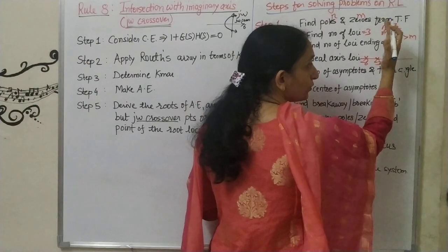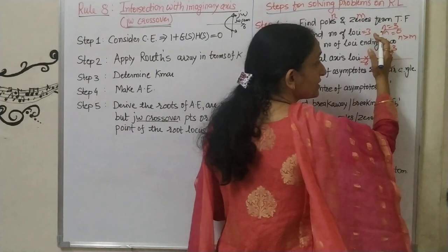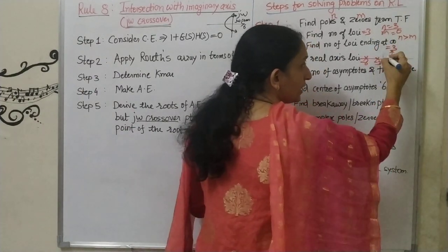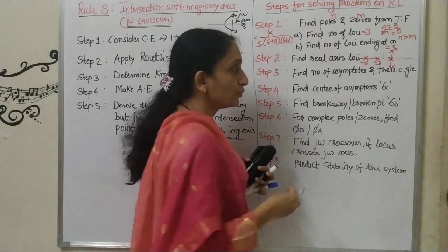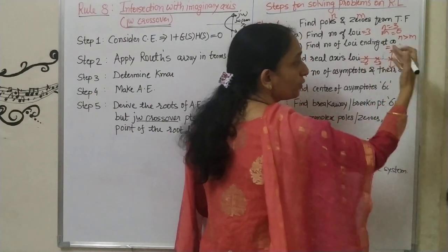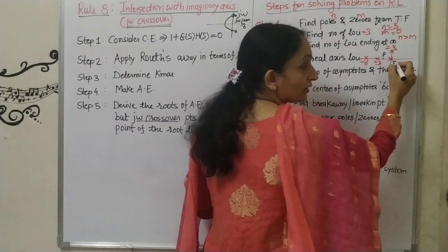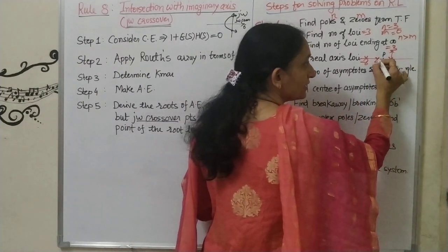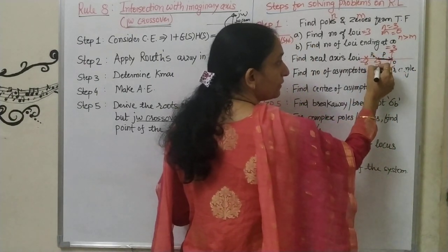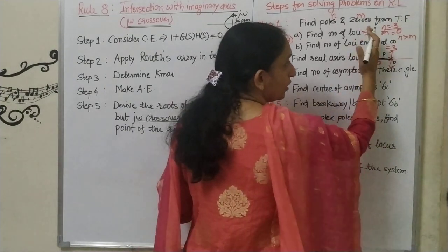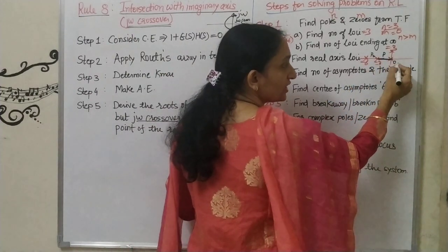Okay, so we know that what we are doing is calculating the addition of the number of poles and zeros on the right hand side of this point P1. If that addition is odd, then that will be the region on root locus. So we can check that here only one pole is there on the right hand side of this point P. So from this pole to this pole, 0 to minus 3, this will be part of the region on root locus. Then here I am considering point P2 in between minus 3 and minus 6. See here, on the right hand side of P2 2 poles are there, so the addition is even, so this will not be part of the region on root locus.